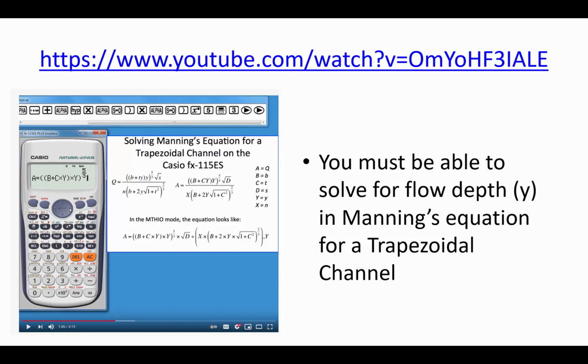because this won't be the last time that you need to solve for an unknown that's inside an equation. So, Manning's equation is easy if you're solving for Q. If you're given the depth and you know the side slope and the channel slope and the bottom width, then finding Q as the output of the equation is simple enough. But when you have to solve for Y, which appears several places in the formula, you can't rearrange that and algebraically solve for Y in a simple way. It's just much better to use a numerical solver.